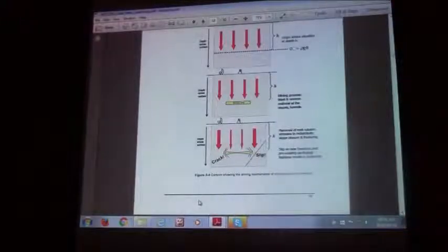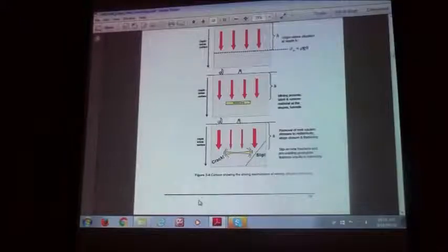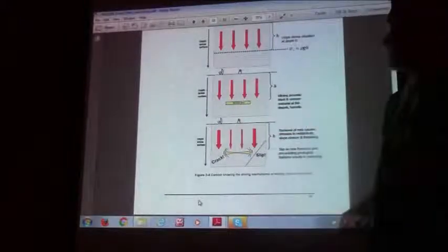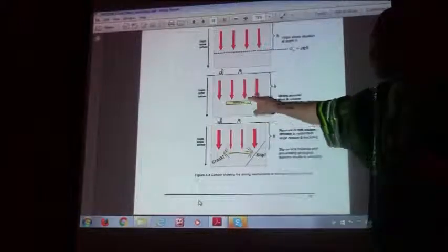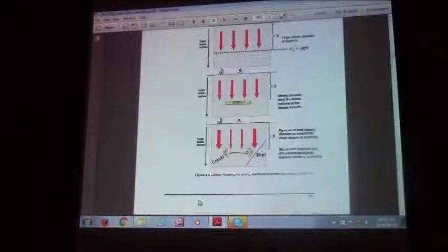So what causes mining-induced seismicity? Well, because you're making an excavation, your stress is being concentrated on the outside, and sometimes that stress will exceed the strength of your rock. If you make a circular excavation, a circular tunnel, this is something you can solve analytically. It's very simple. The equations are known as the Kirsch equations, which predict the stress distribution around a circular tunnel, and what they predict is that your stress will be amplified on the edge of the tunnel by a factor of 3 compared to what we call the virgin stress, without the excavation.